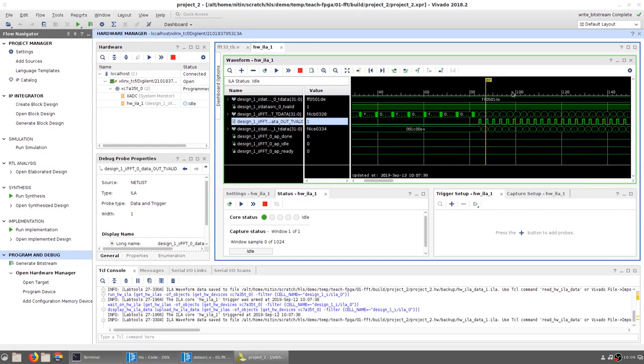So remember that you should be looking at these values only at the places where the output t valid is equal to 1. In other words, when t valid is 0, the values could differ by quite a large amount, but that's not consequential because the value is not valid. But whenever t valid is equal to 1, we find that the FFT out data and the data source_1_t data match quite closely, well within the tolerance limits that we had set.